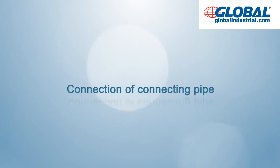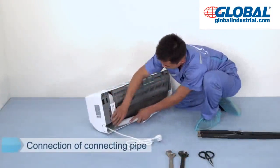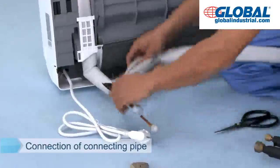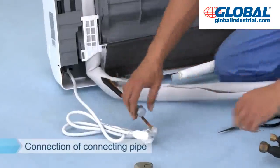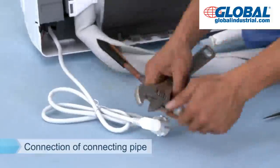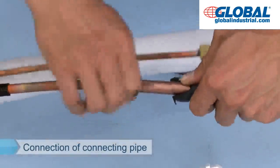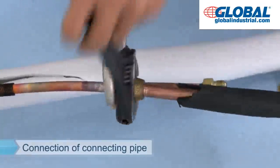Connection of connecting pipe. The input-output pipe should be adjusted to appropriate position at slow speed with even strength. Insulating sleeve is cut 4 to 6 inches to facilitate the connection with copper pipe, and check for damage and bend. Remove nut cap of copper pipe. The cone should be vertical to top pipe socket. When the nut is near the bottom of bolt, tighten it with a wrench. Loosen it moderately after tightening for further tightening.